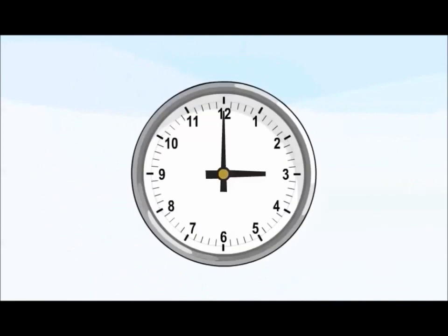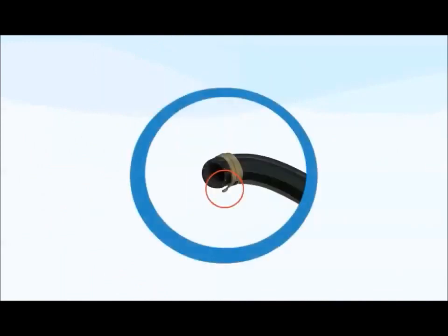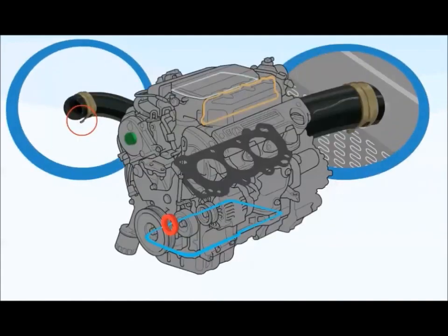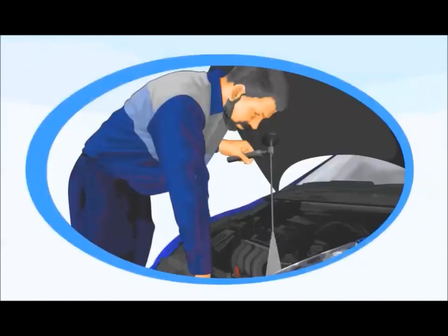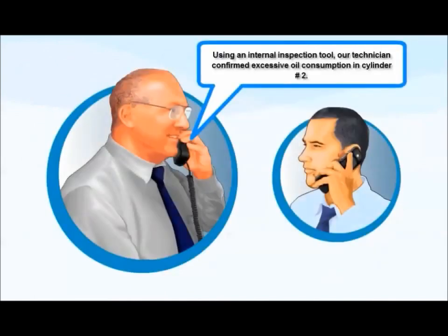A borescope can save time, but it also avoids hassles such as broken clamps, torn hoses, and the cost of new gaskets. Using a borescope to confirm internal problems can also help justify an engine teardown to the customer.